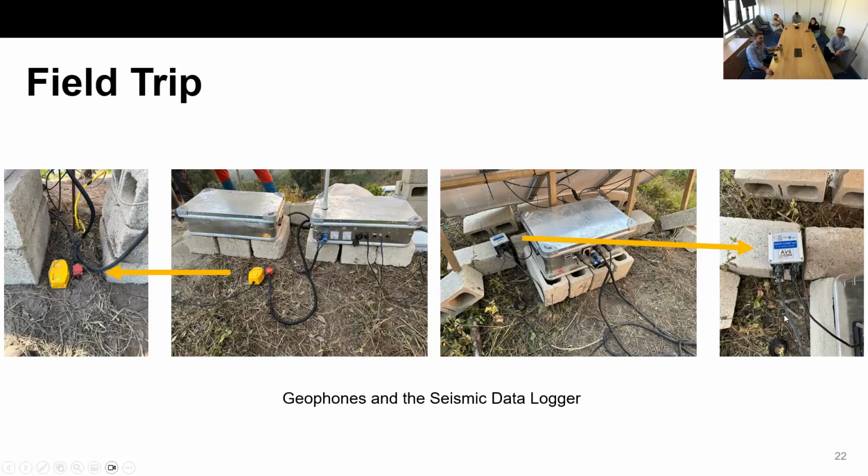It just logs the data, saves all the seismic events happening in the field. And the red, tiny geophone here goes into the box, and this is just for the detector. So we have two geophones, simply. One is to log the seismic data, and the other is to do the real-time processing and trigger the system.